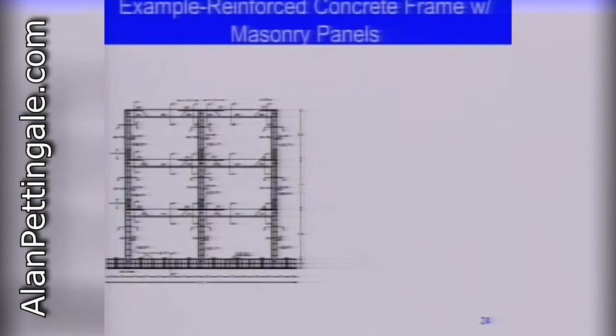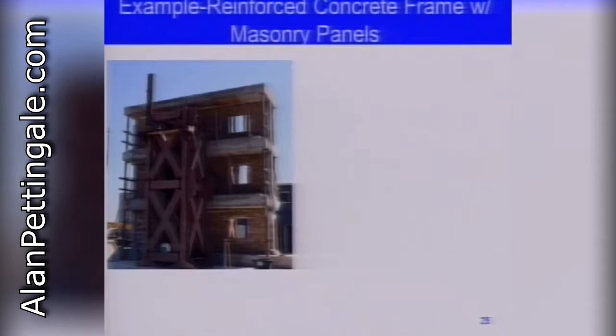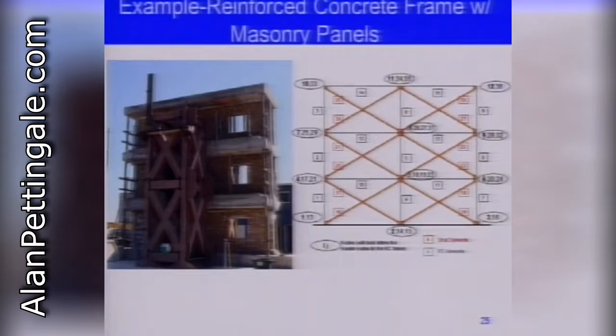That would be the design. It's very inadequate compared to current standards. That's how the structure would look. And that would be a simplified model, because as we said, engineers tend to simplify things. So we would substitute its infill wall, infill panel, with two diagonal struts.